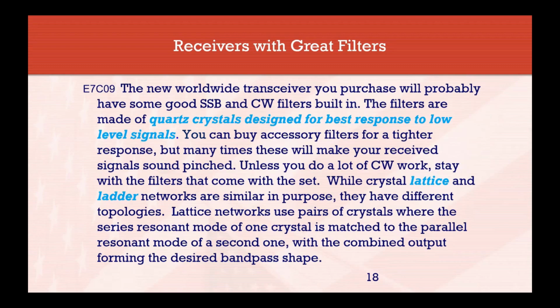You can buy accessory filters for tighter response. In many cases, if you do that, it makes the sound pinched. That is, it makes it kind of a tinny, crazy sound. Unless you do lots of CW work, you can generally use the filters that come with the radio. There are lattice filters and ladder network filters, and we'll talk about that a little bit more. They do mention here lattice networks use pairs of crystals in parallel, so two matched crystals side by side. You'll see that reference a little bit later on.